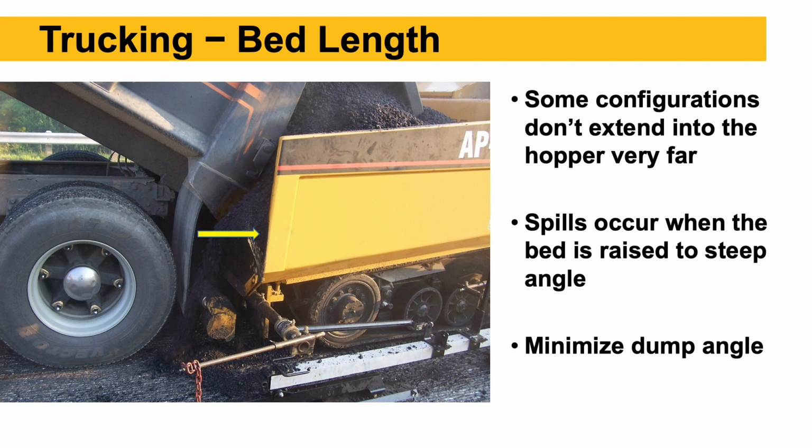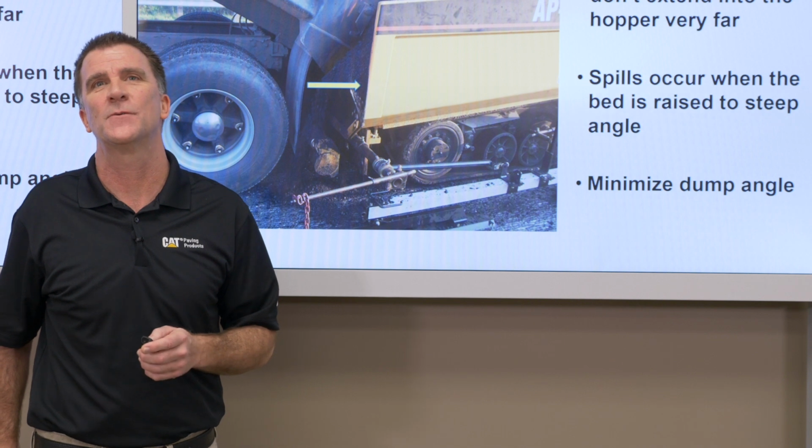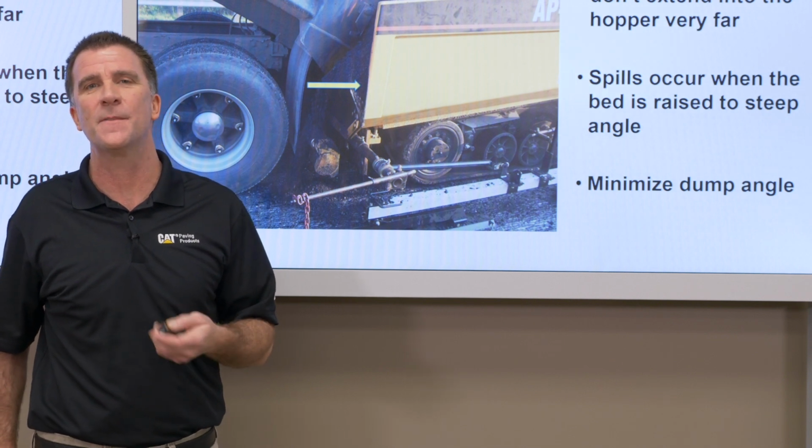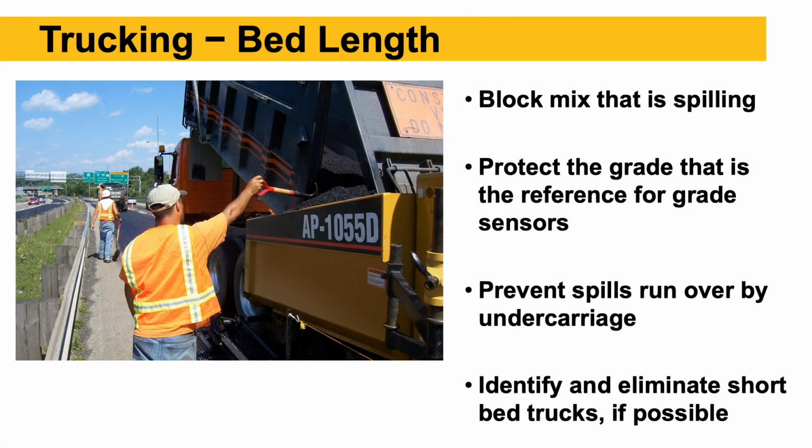Ideally, we want a truck configuration and adjust those push rollers on the paver so that we don't end up with that spillage and the flashing on the paver hopper. This guy in the picture here, he's using a shovel to kind of block some mix from spilling onto the grade, again, just because it's not the best setup for the truck bed fitting into the paver hopper.